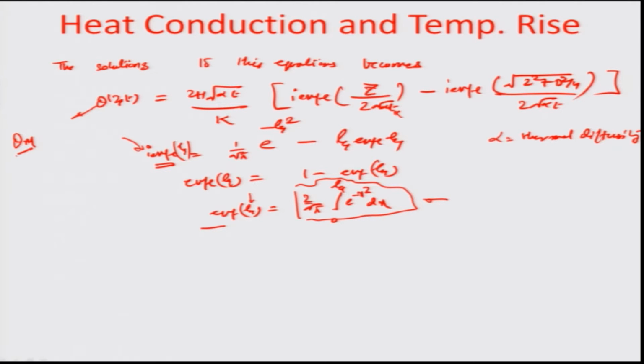So, in a way, for solving for T, you will have to equate this theta to the theta melting, assuming that there is a constant heat addition on the surface up to an extent of a diameter, let us say capital D. You can try to find out what would be the Z value as a function of all these different parameters, and at a certain point of Z the melting would stop taking place, and that is really the boundary where theta equals theta m.